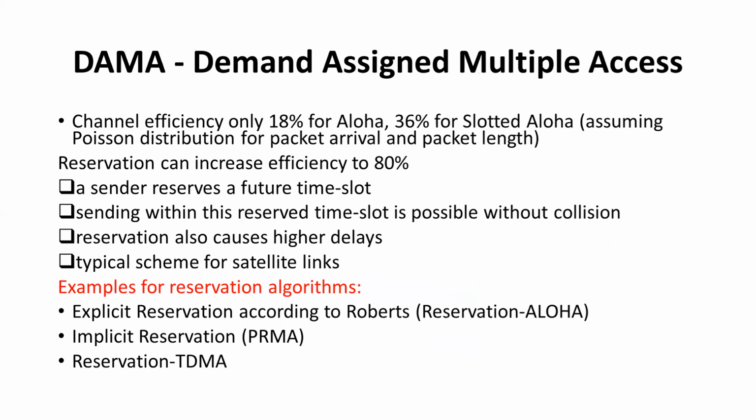Demand assigned multiple access. Channel efficiency is only 18% for Aloha, 36% for slotted Aloha. Reservation can increase efficiency to 80%. A sender reserves a future time slot. Sending within the reserved time slot is possible without collision. Reservation also causes higher delays. Typical scheme for satellite links.